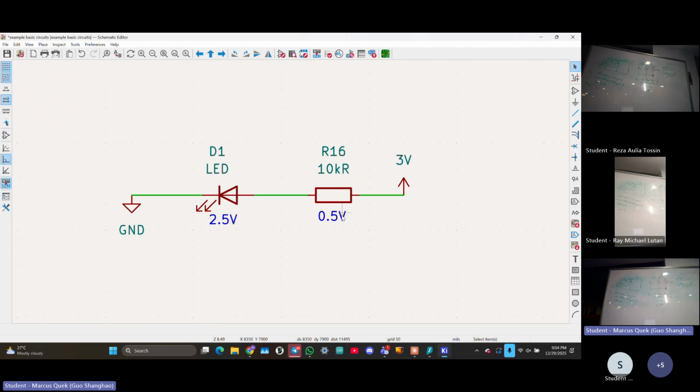I've also got this power line at the side, plus and minus. This is where I can put ground and whatever high voltage I want to use, anything higher than ground. I can plug things into the sockets and wire things up this way. If I put something on this row and something else on this row, those two things are connected because they're on the same row. So I can use this to wire together basic circuits.